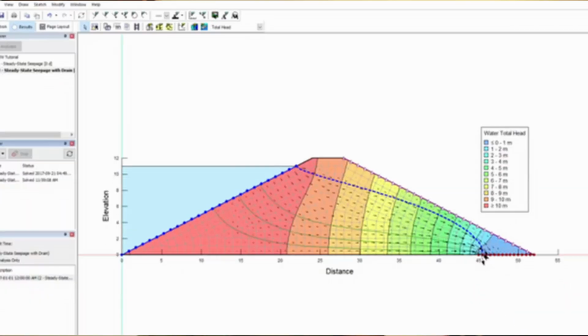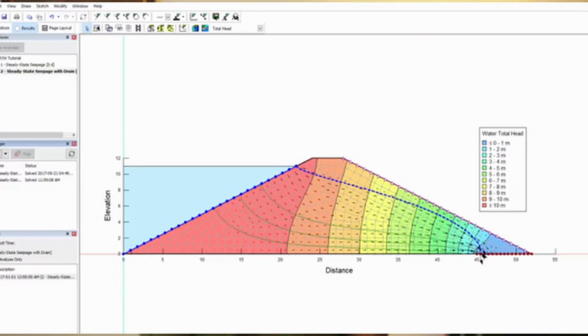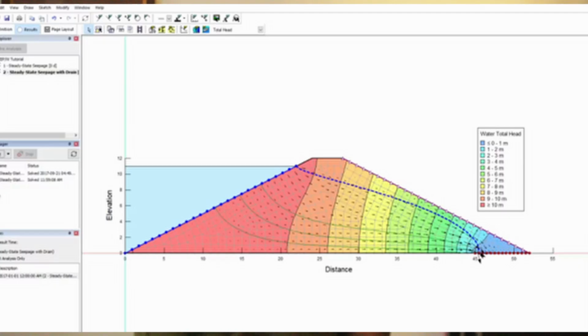This can be commonly seen in one of the models I generated using GeoStudio software, where you can see how the water path is moving along the embankment and the toe channel in terms of the flow net to a point at the downstream side. This means the soil around this section is going to be swept out by the groundwater force and taken to the downstream side of the reservoir. Soon we are going to learn how to handle such a problem.